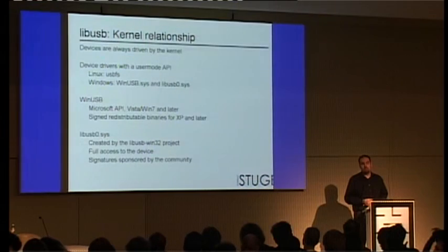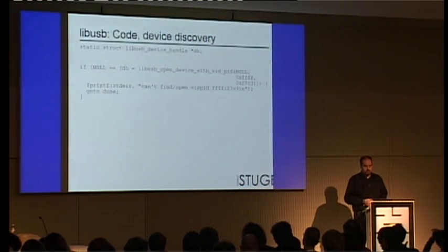With WinUSB or with the libusb0 driver? The libusb0.sys driver is nicer because it allows full access to the device, whereas the WinUSB driver only really supports interrupt, bulk and control transfers. It doesn't support isochronous. Too bad. The libusb0.sys driver has also been signed, sponsored by the community.